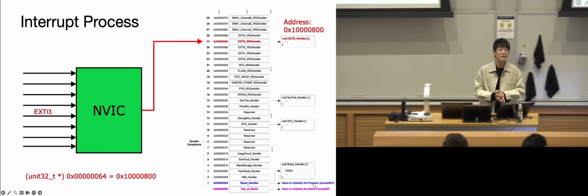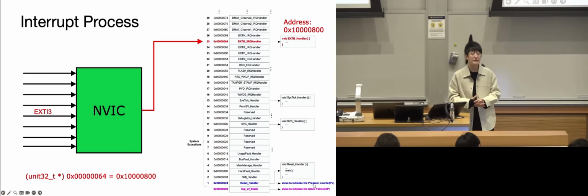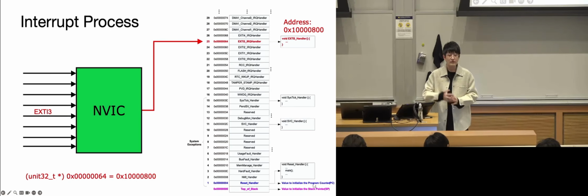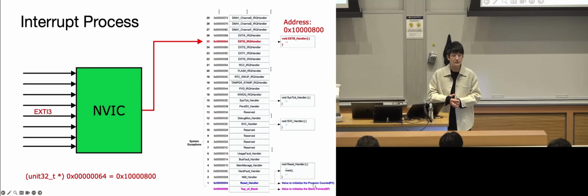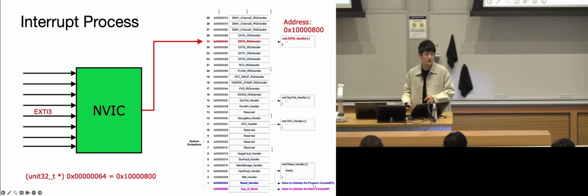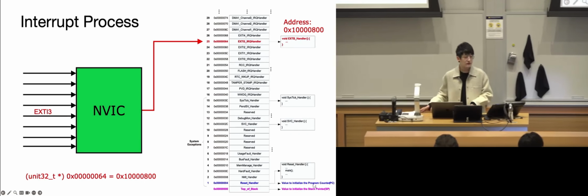I just have a quick clarification. I know that the NVIC has pending bits for each interrupt number, but at least on STM32, doesn't the GPIO external interrupt also have its own pending state? I recall hearing that, like a buffer.